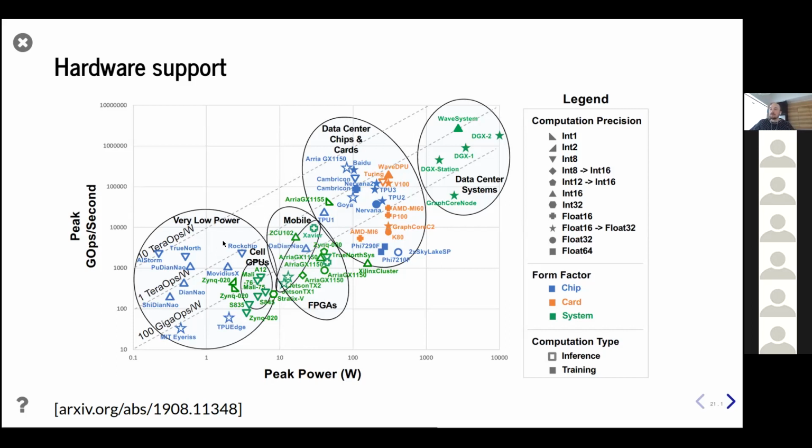And then you have these very low power systems, which, for example, are dedicated ASICs, but also now you can do very low power inference even for convolutional models and for some larger models using FPGA platforms and some available frameworks that we have now to be able to target these platforms more efficiently, which has not previously been available.